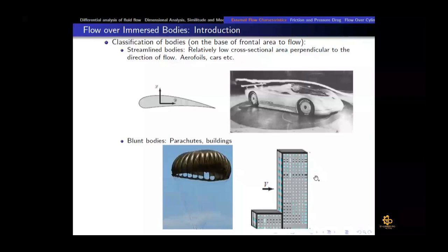And the other drag component is the wall skin friction drag. Skin friction drag is due to the wall shear stress tau omega times the surface area. So for the streamlined bodies, the skin friction drag is more. Skin friction means that it is due to the shear stress on the surface, and pressure drag is very less because the frontal area is very small, because there is minimal flow separation in the wake region, right?